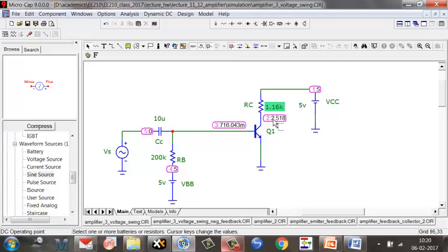And where do you get? Can you see, it's almost in the middle. 2.5. The first two refers to the node, so I can remove this if that's causing confusion. So the voltage at this particular node is 2.5, almost in the middle. So a bias in the middle. What would you expect? I should be able to get a swing as large as 2.5.